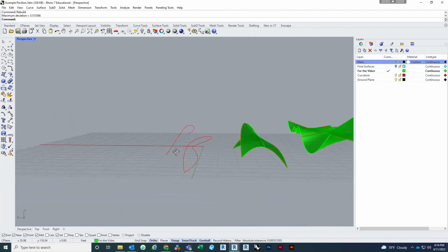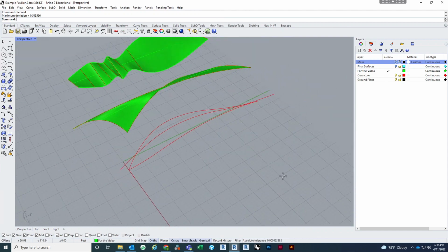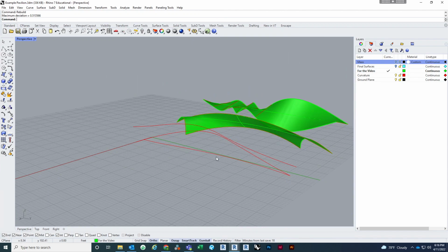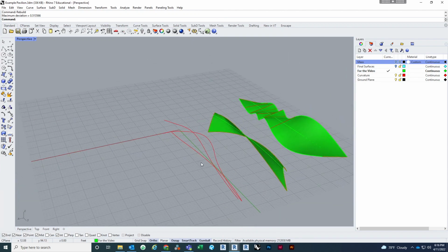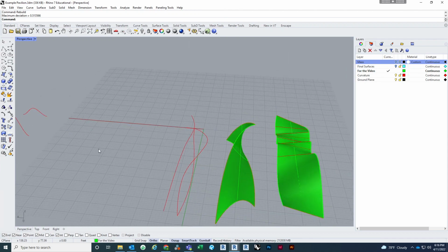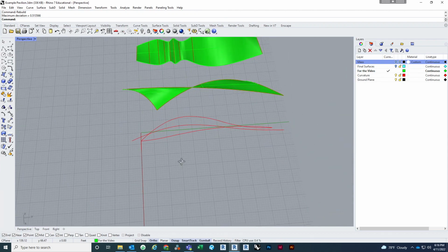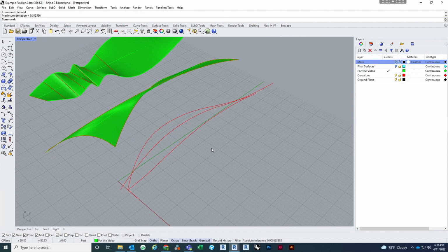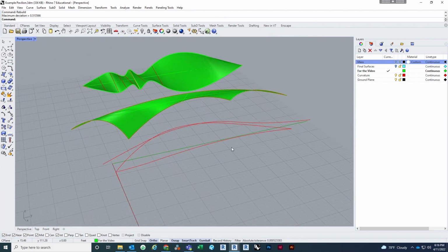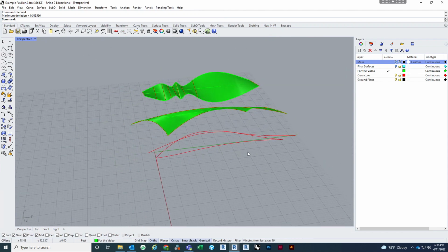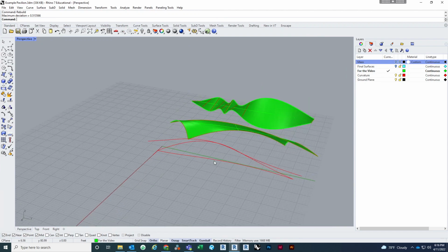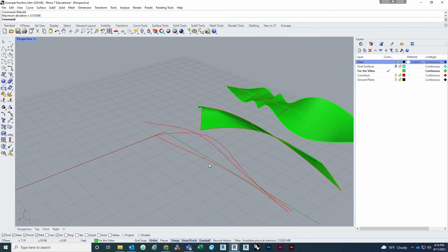Now, when I am creating my curvature and exploring different geometries and massings, I typically try to stay with a low point count, and then add as I go. If I get a form that I really like, but I want to add a little bit more detail or curvature in one end, I'll add control points to it.